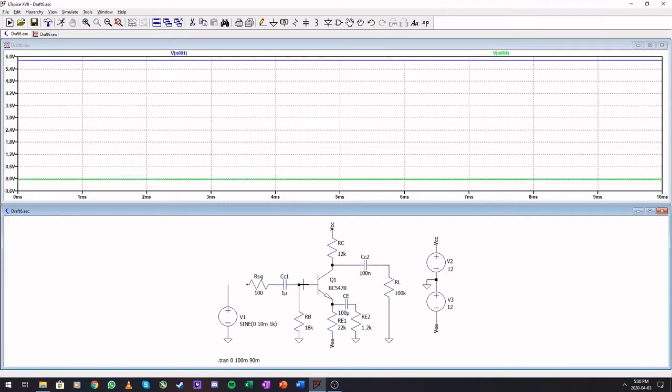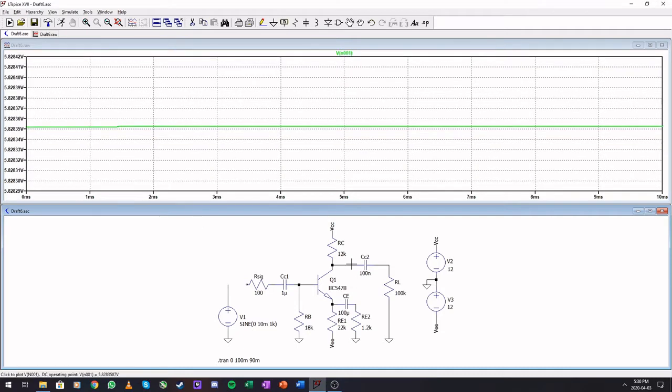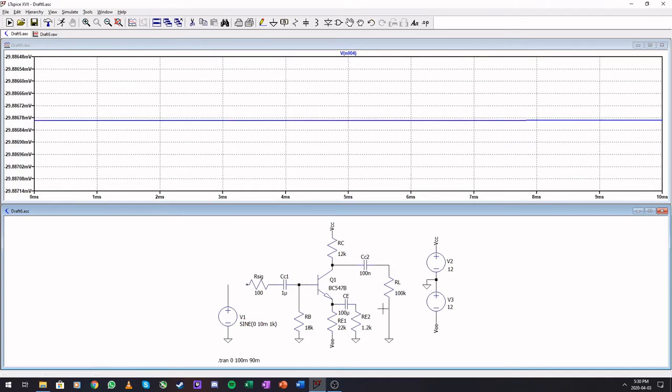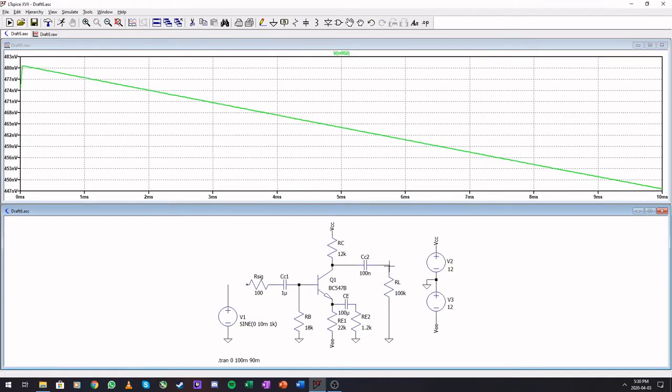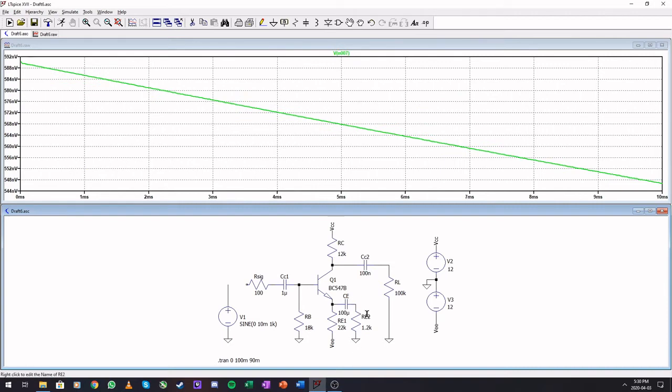Okay, so you can click at any point in the simulation. See, this should be close to minus 0.7 volts. This node, it's very close, we can see our DC values. Okay, also, if you click on this side or that side, you shouldn't typically see anything. This is nanovolts. So, in terms of DC, this and that is not visible to our circuit.